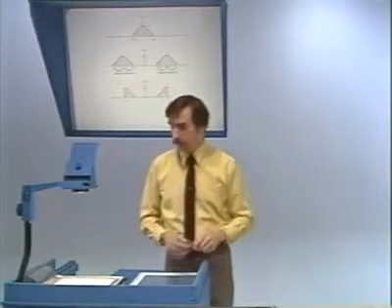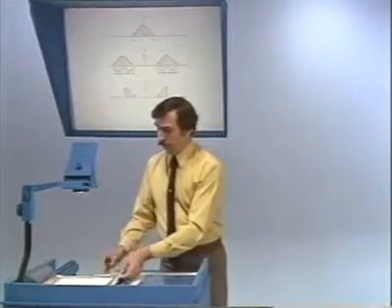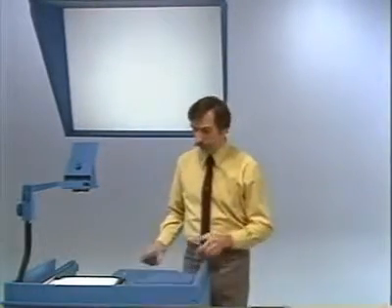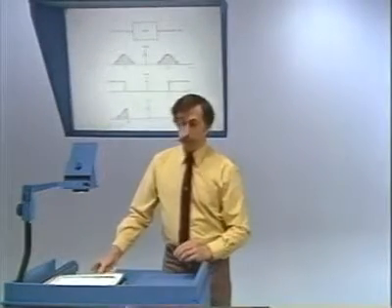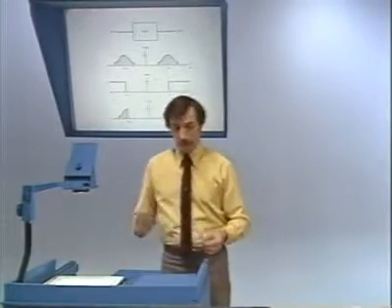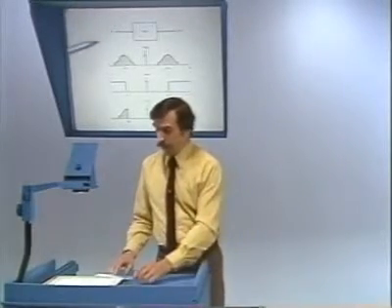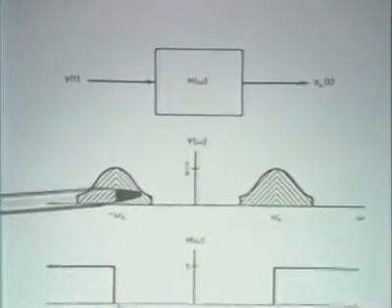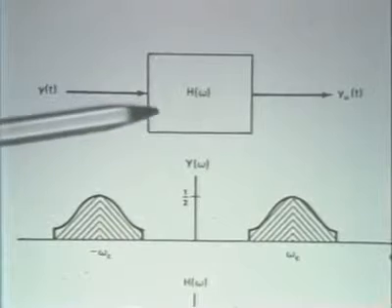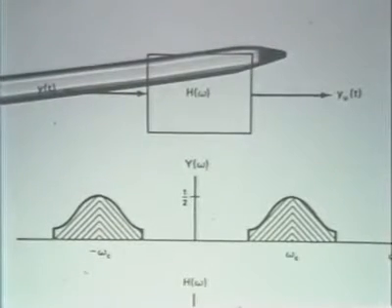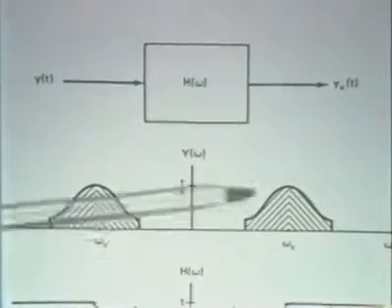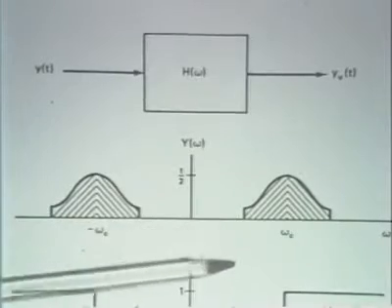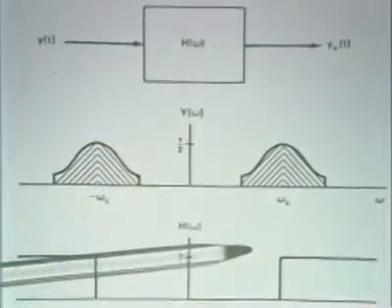There are a variety of ways, and there's one procedure that is discussed in more detail in the text, which uses what's referred to as a 90-degree phase splitter. The simplest way, at least conceptually, is to think about doing it with filtering. The idea simply is that if we have our modulated signal, here's the spectrum of the modulated signal, and if that modulated signal is simply put through a high-pass filter, then the result will be to eliminate the lower sideband, if we choose the high-pass filter to have a characteristic as I indicate here.